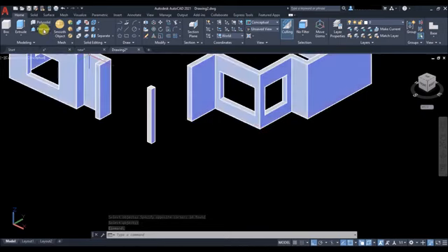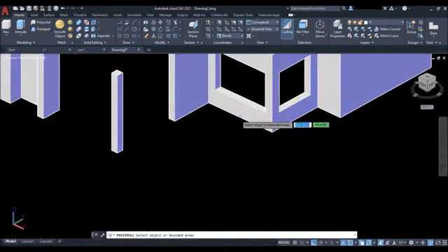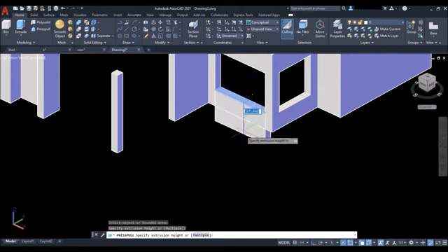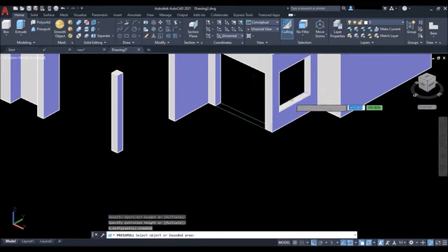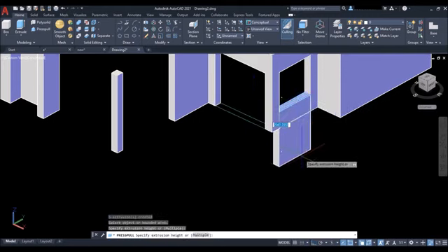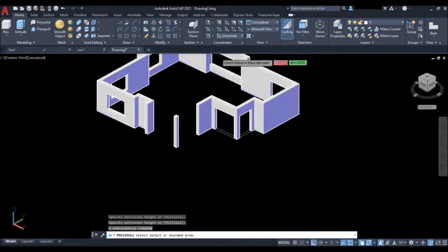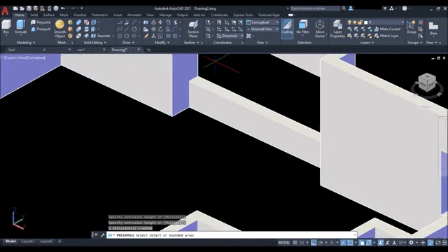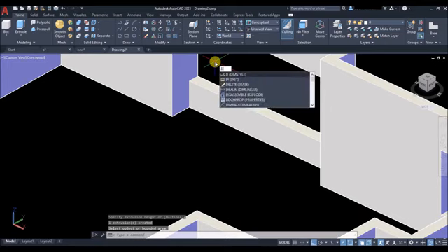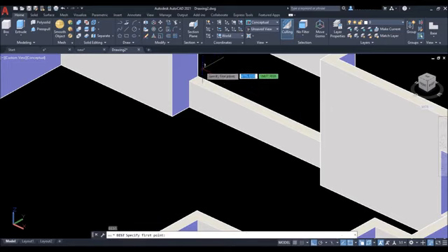Now click on press pull tool. This is the main door. So select this face and press pull cut it downwards. This one as well. Right click to exit. I'll check a few distances by using dist command.